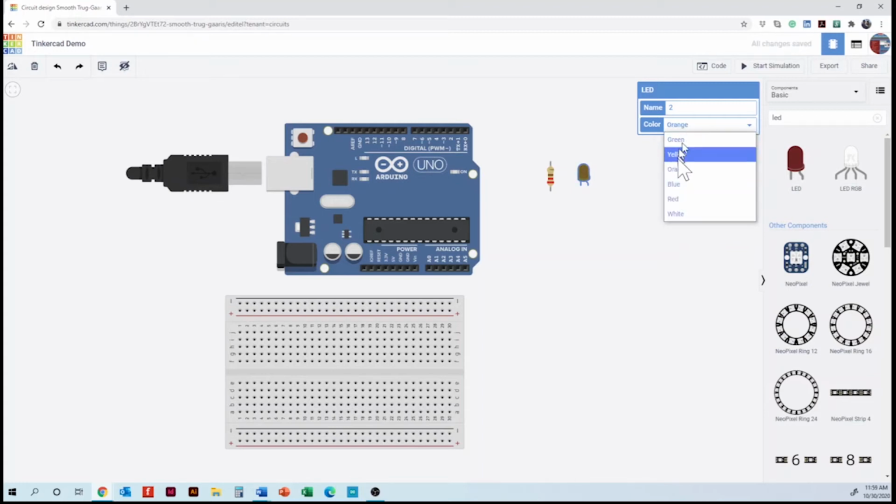And as well, if you click on every pin, every leg of the LED, you will see the connection. We have cathode and we have anode. Cathodes are gonna be connected always to the negative side or ground. In electronics is represented in blue. And the other leg is the anode, or is the positive, represented in red.